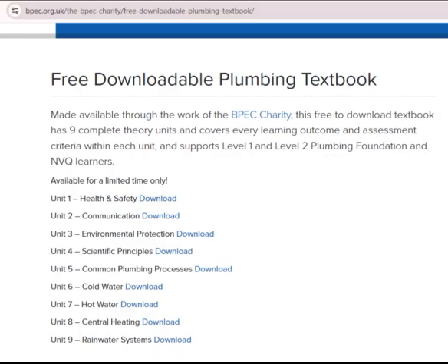Lubricants/greases. A lubricant is a substance, often a liquid or a grease, introduced between two moving surfaces to reduce the friction. This improves efficiency and reduces wear. There are many types of lubricants used in the plumbing industry. Silicone grease and spray. Used for general lubrication of plumbing parts for water and drainage systems. It is also used when jointing push-fit plastic pipe jointing systems to lubricate the rubber seals. Graphite paste, used for lubrication of gas taps.